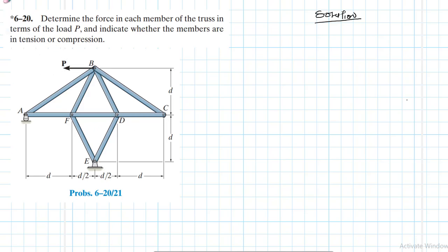You could do your calculation by applying the equations of equilibrium at joint C, and you would still find CB and CD to be zero force members. So the two are as good as not there. It's important for trusses to do a quick visual inspection to check for zero force members so that your calculation time is lessened.